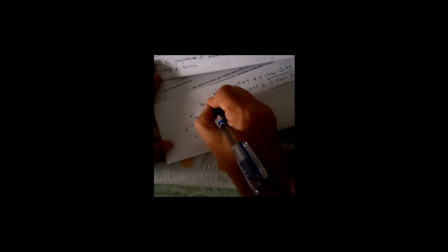Now what you have to do, it's given B dash is 50 mm above the XY line. So previously, take 50 mm above and draw a projection line. That is, the distance between this line and the XY line should be 50 mm. So this is the locus of B dash. Locus of B dash is that. Now AB is parallel, we know. Then the last point is the distance between end projectors is 50 mm.